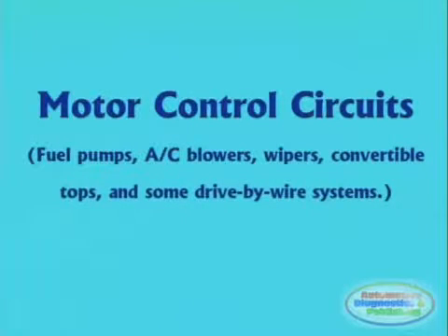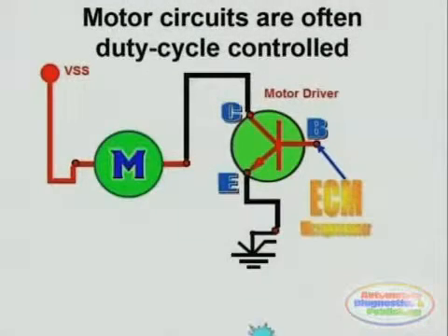Duty cycle control motor circuits are employed in a wide variety of components such as fuel pumps, AC blower motors, wipers, and any system that requires varying motor operation. In this case, we see how the motor is duty cycle controlled by a driver or transistor. Again, the same principle applies.